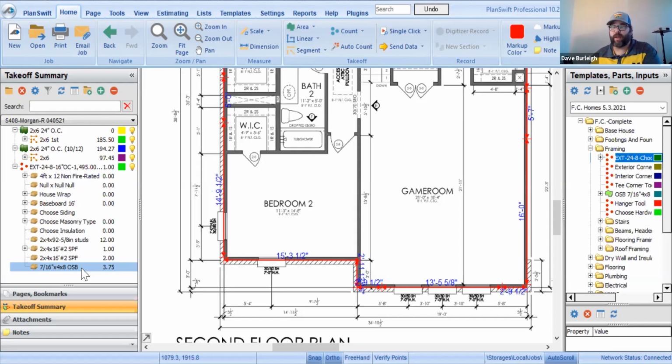Then when I talk waste, I'm only talking true waste. What percentage of my studs do I need to account for being twisted, having huge knots in them, the occasional miscut, things like that. But I don't need to just throw this huge, 10 to 20% waste factor because I know that maybe my estimating wasn't spot on to begin with.